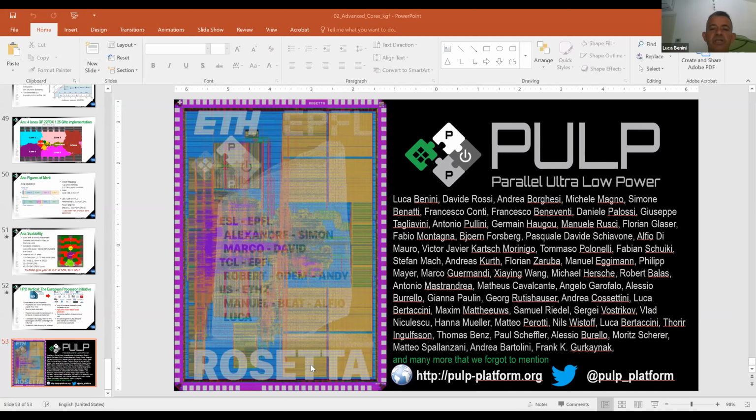Is there a standard RISC-V extension for a transprecision floating point unit? No. This is a typical case where they went ahead with a non-standard extension. We are seeing a lot of traction around this transprecision floating point unit, and I expect that what will happen is similar to what happens with our XPulp instructions, that are becoming a proposal within a standard specification group. The XPulp instructions were described by Frank in the previous part of the lecture. They become part of the DSP standardization group and are gradually being transformed into a standard.